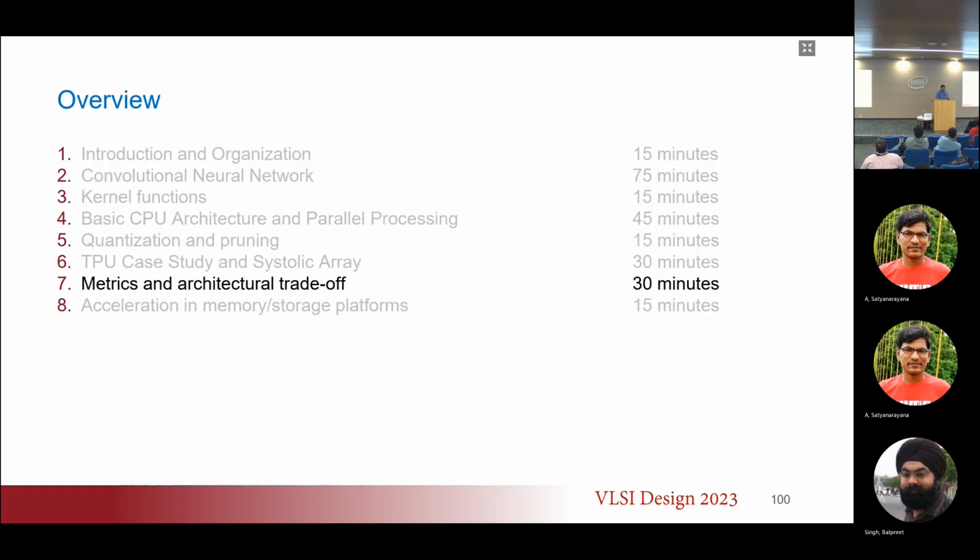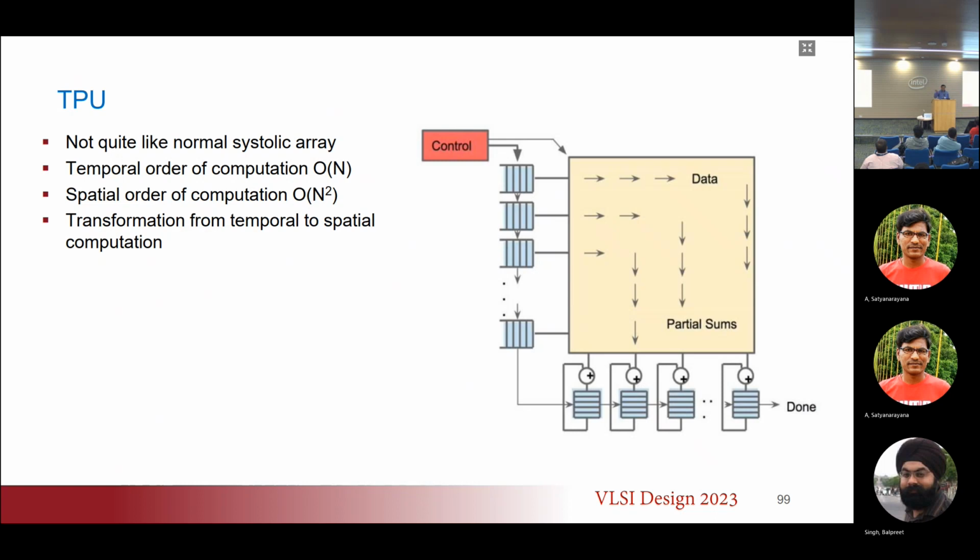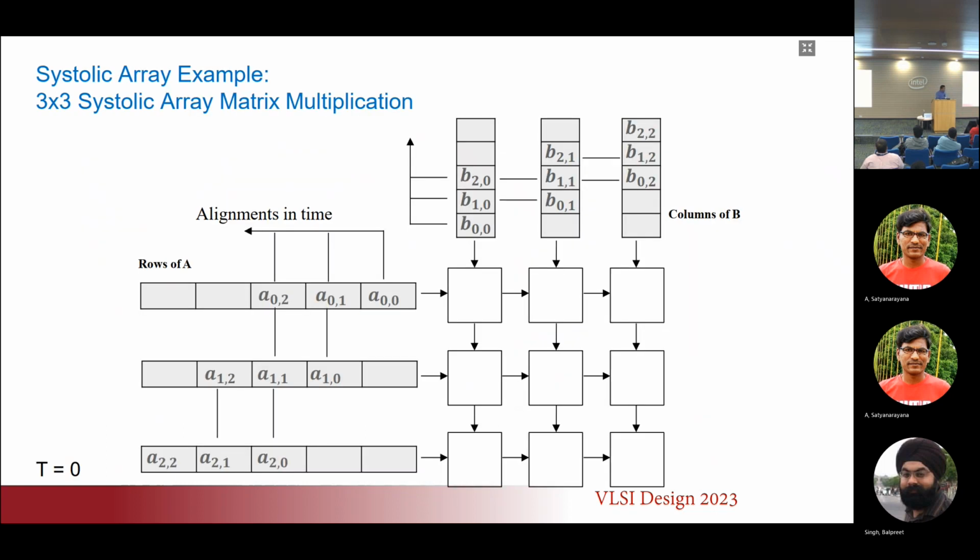And eventually, when you have applied 2n minus 1 clocks, the entire computation is going to finish. So that's the core of that matrix multiplication unit. It's called a systolic array. It's a good point to discuss some of the elements. It would basically need a staging buffer for the shift registers, and it needs data alignment, and then we need to kick off. Staging this memory is a copy operation.